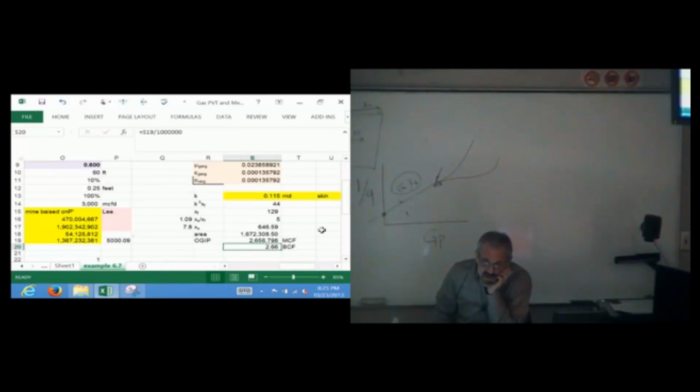Except for the fact that this is synthetic, and I've never seen a pressure transient analysis go from linear flow to radial flow. This does depict everything that you might want to do with linear flow, except for the fact that we have limited ourselves with the Greengarten type curve to what conductivity? Infinite conductivity. When we try to plot finite conductivity on the Greengarten type curve, we'll have a little bit of a problem. But I think that's a good place to end tonight's work. Question?